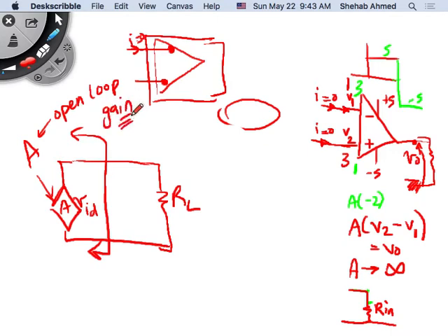Why is this called open loop gain? Because again, it's a very big number, and we saw that anytime you put a voltage multiplied by this open loop gain, the op-amp will saturate. So obviously we're going to come up with a closed loop gain after we add some components that make the circuit useful. When we use it as is, just op-amps, and we put some voltages at the terminals, the open loop gain will control my output.